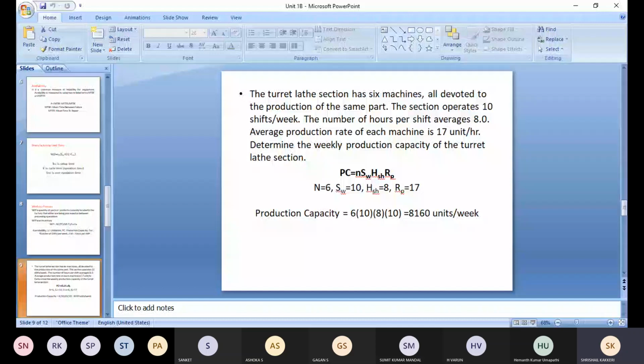Non-operation time will be reduced. That is what the strategy is. And simultaneous operation. Simultaneous operation is on a single job on a machine, more than one operation will be done at a time, not one after the other. When two or more operations are done on the part at the same time, that is called simultaneous operation.